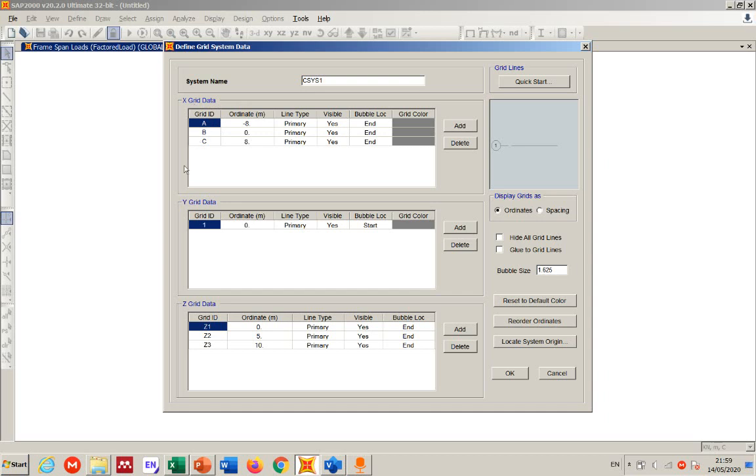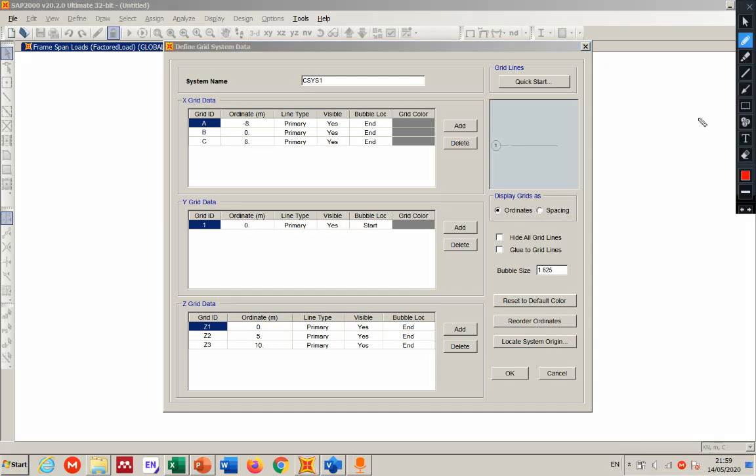X for us basically means that we are working in x direction and in the z direction. I have it here. This is the z direction you're working here. So in the x it tells me -8, there is -8, then there's a 0 somewhere as a coordinate they're using, imagining that this is z will be somewhere in the middle. It doesn't matter, this coordinate, you can change them. Then I have coordinate 0, then I have coordinate -8. So the distance between them is 8 meter, as we specified there.